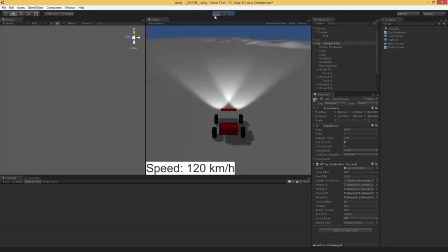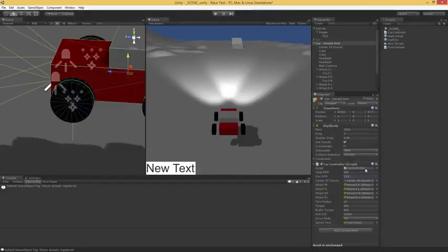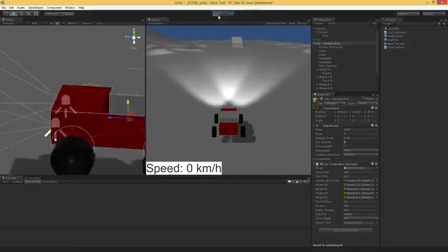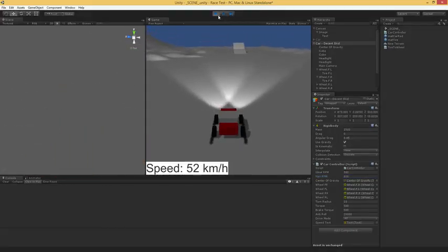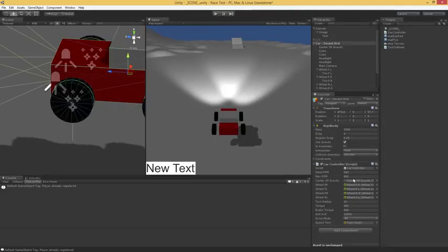But by tuning it to about 500, you get less of that skidding effect, and instead you get a better sort of midline speed. And the top speed is basically based on this max RPM. If I were to drop this to, say, 800, you'll see our top speed will change in accordance with that. Again, the collider, I think I'm using 0.6 as the radius of my tires. So there's a direct relationship between the max RPM times 0.6 and what we get as our max speed there. Because once we hit that speed, we can't accelerate anymore. So I'll go back and put it at 1100.